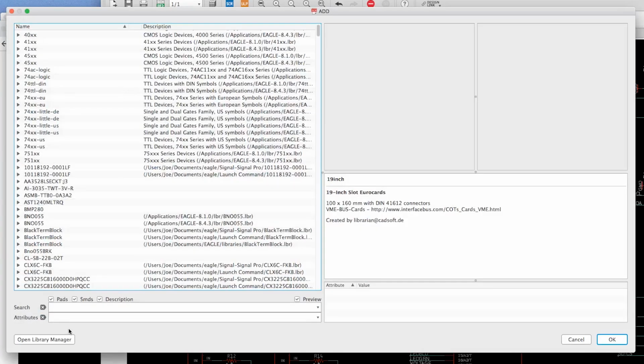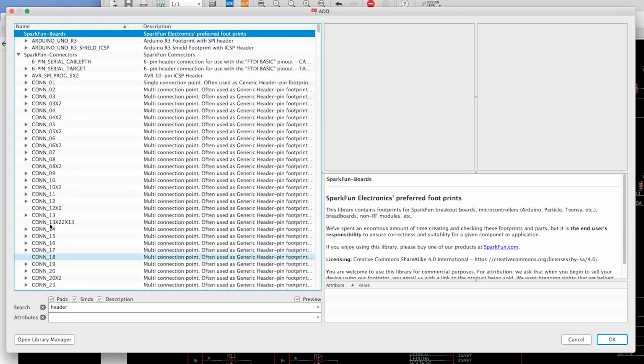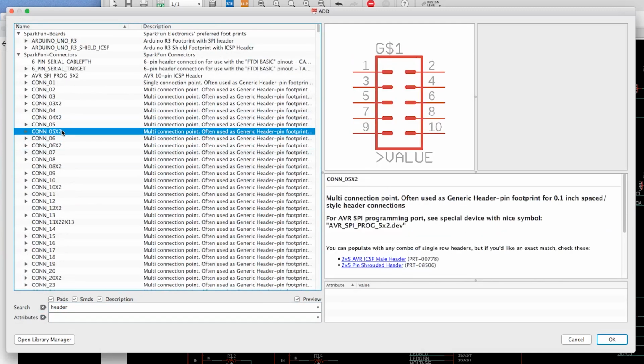We have just one more thing to do, and it's that I wanna break out a bunch of extra pins so that if people are using this and they wanna experiment, they can just use the other pins, or they can connect other things to here. So let's add some header pins onto this computer. To do this, we're just going to use a standard header pin, and I want 10 pins total to be broken out. So I'm gonna go into the parts list here, and I'm just gonna search for header. Here we go. And I want it to be a 5x2 pin.